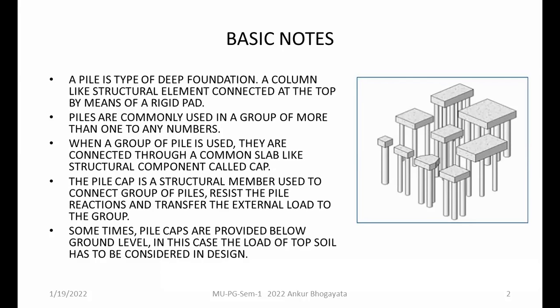So we should understand that the primary function of the pile cap is to transfer the superimposed load, that is the applied external load from the superstructure, as well as it is subjected to the reactions by the piles. Because by principle, if we understand pile foundation, it transfers the force to an adequately strong bottom, right?